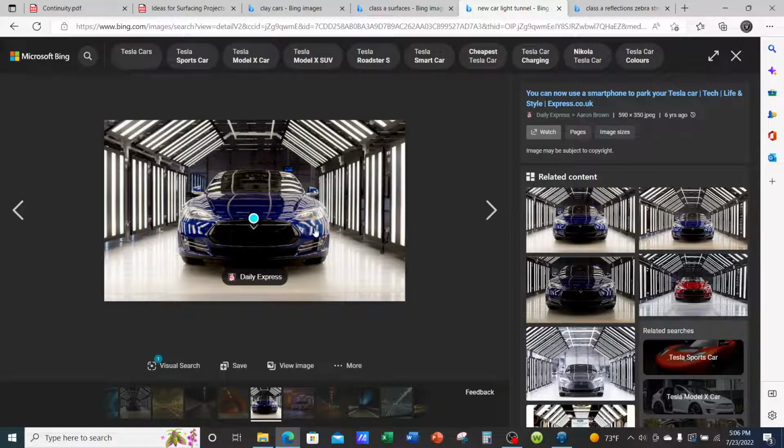Here, this is G1. So this is a sharp edge, and in this case, obviously, is intentional. You can also see it on the left side, a lot clearer. The reflection lines all of a sudden disappear as you transition from this surface and go upward towards the headlight. Okay, so obviously this is intentional, so we have a sharp edge. We have G0, point continuity. We don't have tangency, we don't have curvature as you transition from one surface to another.